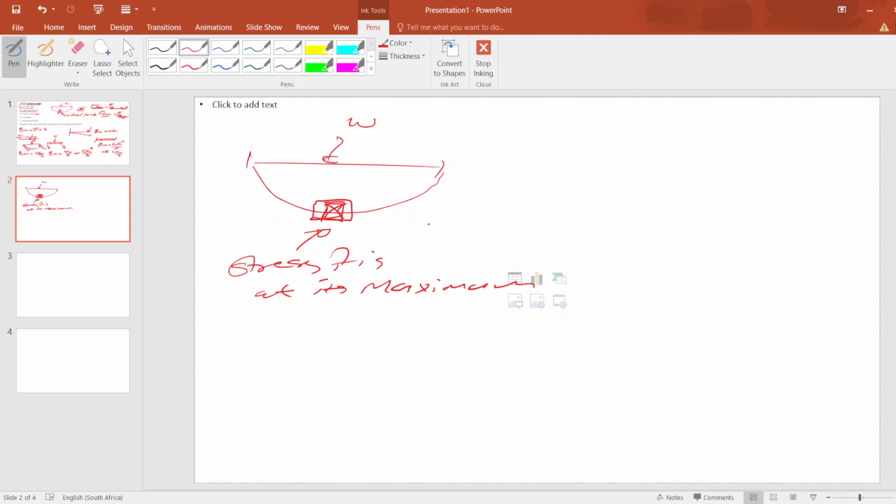It could be a tensile stress that is dominating, or it could be a compressive stress, but we then have to determine. Now, when you have the force applied on your beam, this is what you'd realize. The forces inside that beam are causing compression, because they are converging. Then outside the beam, you'd realize that the beam is being pulled away, or stretched. That means at the bottom, the force that is dominating is what?